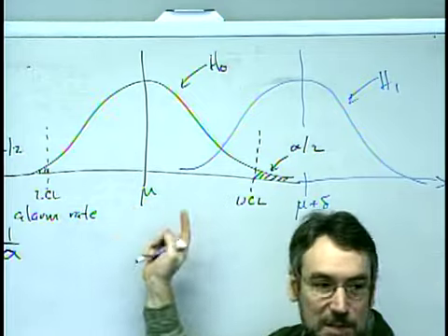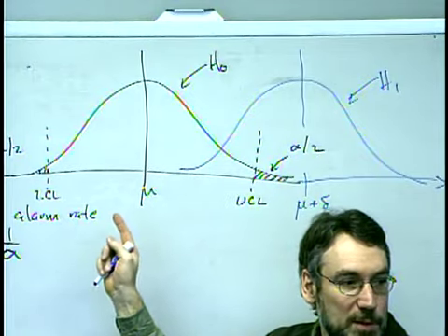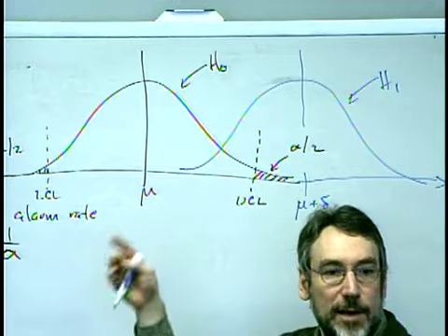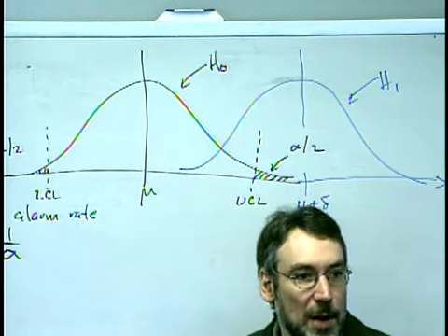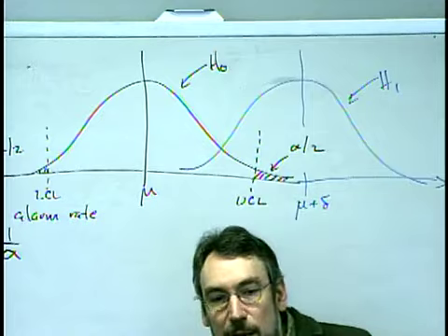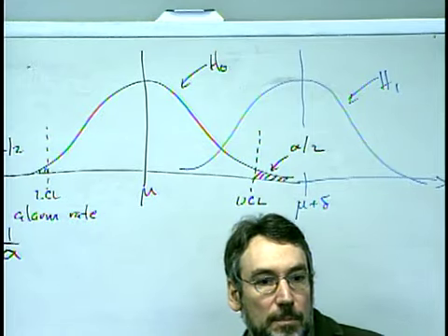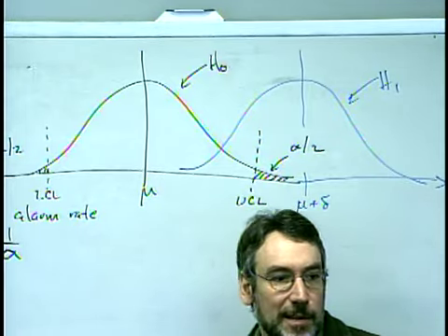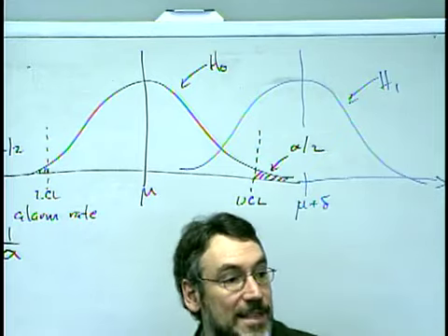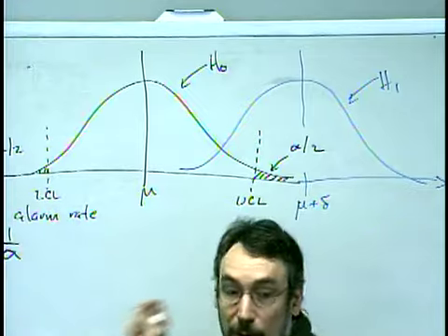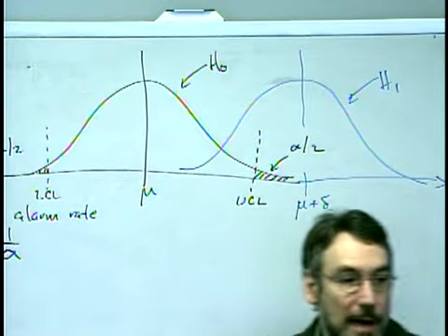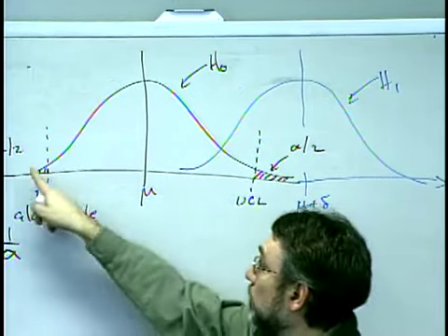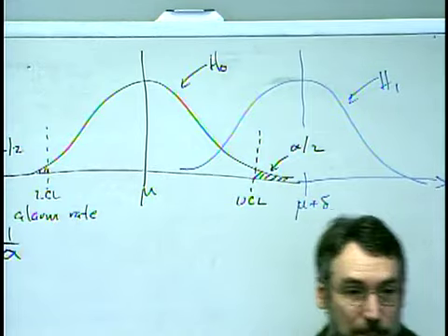By the way, there's nothing magic about plus minus 3 sigma. If you don't want to respond three times out of every 1,000, or about once every 333 runs, you don't want to respond to a false alarm rate. It doesn't cost you that much to have a false alarm, or it costs a lot to have a false alarm, but it doesn't cost you that much to have a bad part. Then maybe you only want to respond 1/10 as much, in which case you would change your control limits, move them out a little bit so that you set it based on the average run length or the probability that you can accept out in the tail.